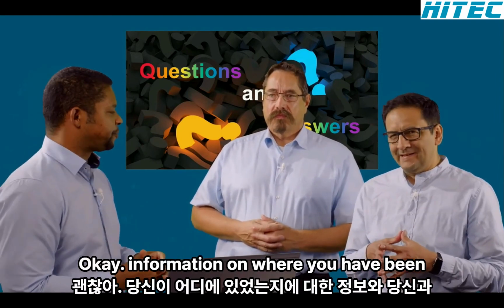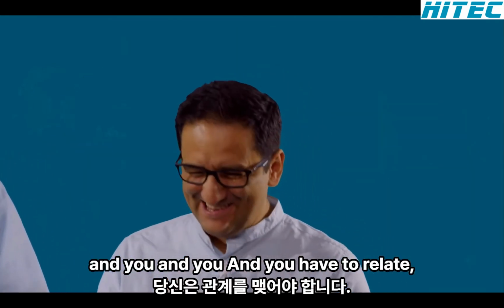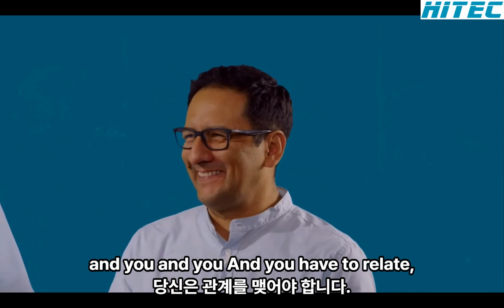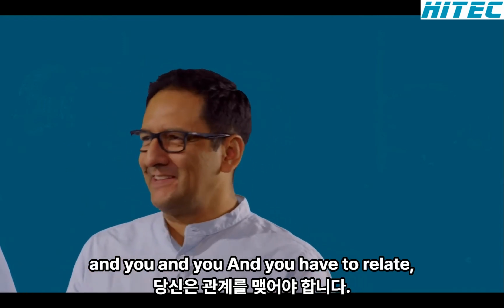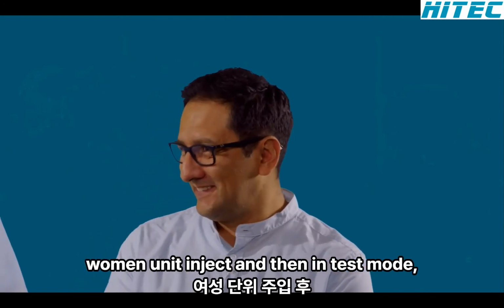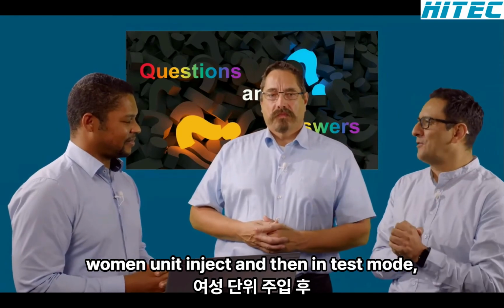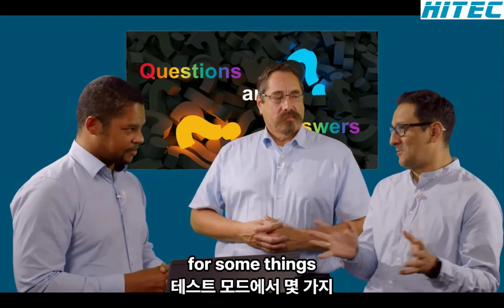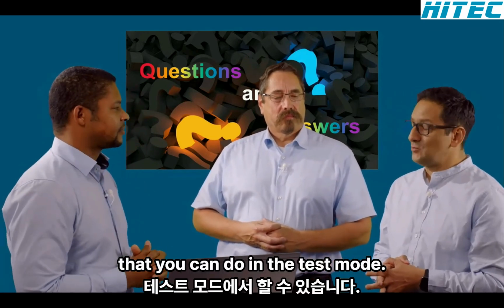Okay. In the conventional way, you have the test equipment, and you go to the station and you inject the currents to the device. That's one way. Now you have the merging unit, and you have the relay, the subscriber. Then you can go also with the test equipment to the merging unit, inject signals, and then you can use, for example, the test signal to put a whole device in test mode. That is one way. You can test the complete device. You can test per function. You can test per stage. It's a variety of things that you can do.